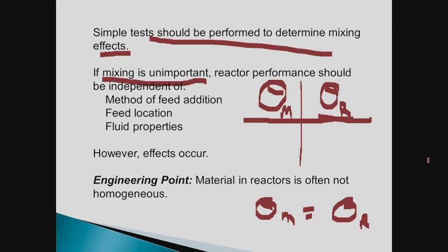If you have the situation where mixing doesn't really matter, then the method of feed is unimportant, the feed location is unimportant, fluid properties are unimportant. However, if you have mixing causing the reaction, and the reaction time is equal to the mixing time, then you do have effects of feed method, feed location, and fluid properties.